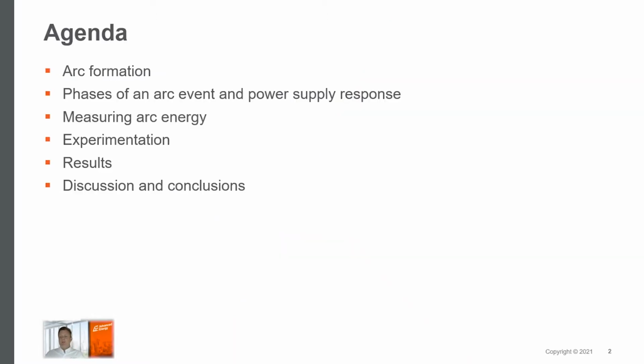Arc energy continues to be important and critical due to the increased process powers, the known relationship between particle size, arc energy, and increased output powers. Requirements continue to become more stringent around allowable particle sizes as the film properties and structures become more sophisticated and feature sizes decrease. The need to better understand arcs and the parameters used to optimize them, and at times control the energy into an arc, becomes more critical.